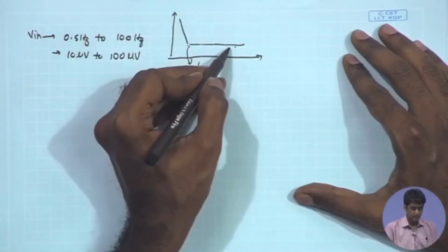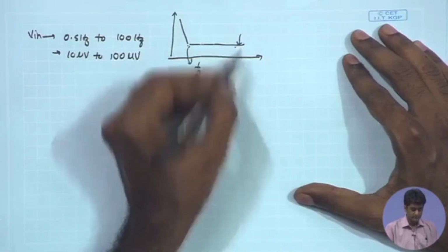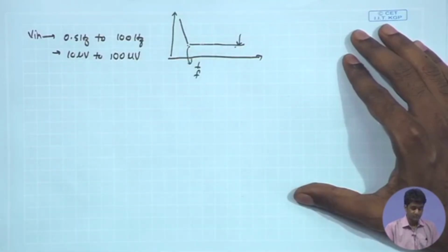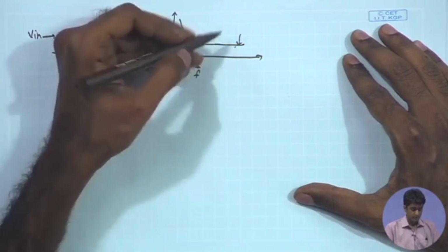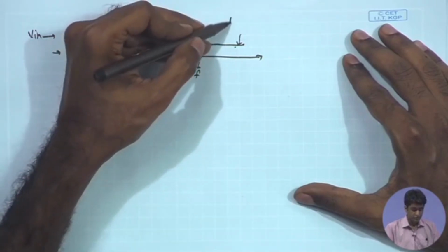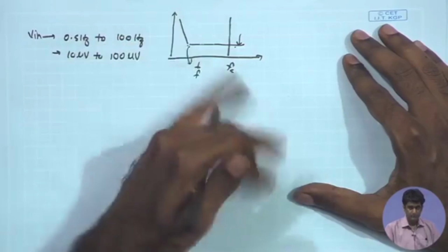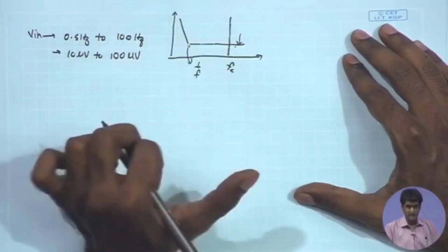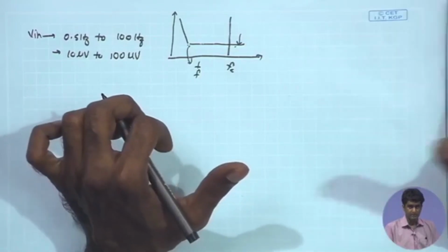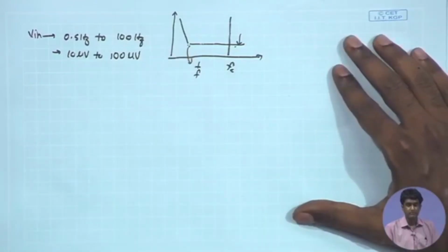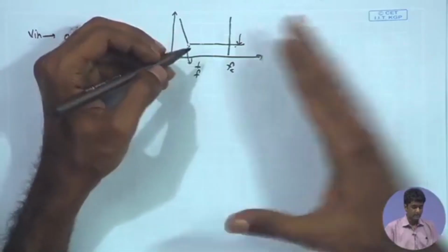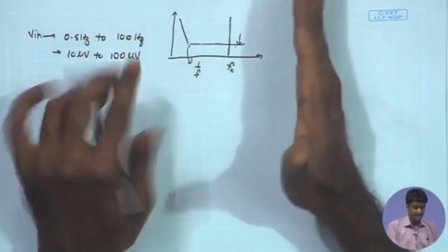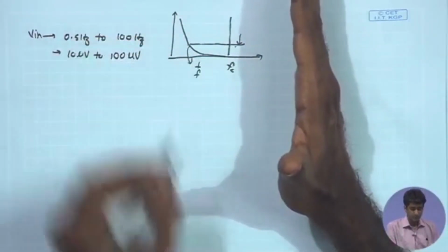Likewise, another target is to minimize the white noise level of the noise spectrum. Once we have done that, we decide the chopper frequency fc with which we are going to multiply the signal, and we assume that fc is sufficiently higher than the 1/f corner frequency, maybe at least 4 or 5 times higher, so that the input signal is sufficiently isolated from the 1/f noise spectrum.